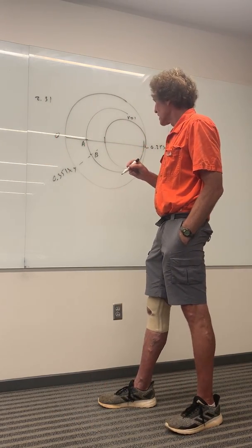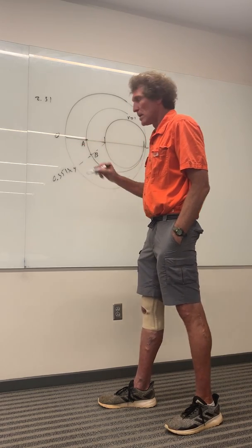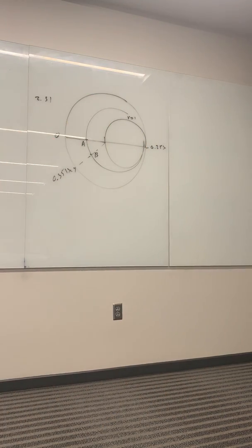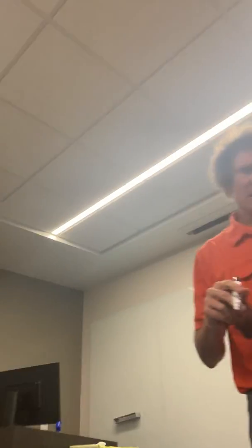And then this coax cable is terminated in a short circuit and then in an unknown load. Okay, but the short circuit is what? Can somebody just read the problem entirely? It says a 50 ohm slotted coaxial air line is terminated in a short and then in an unknown load. Determine A, the measurement frequency, B, the VSWR when the load is attached, and C, the load impedance.